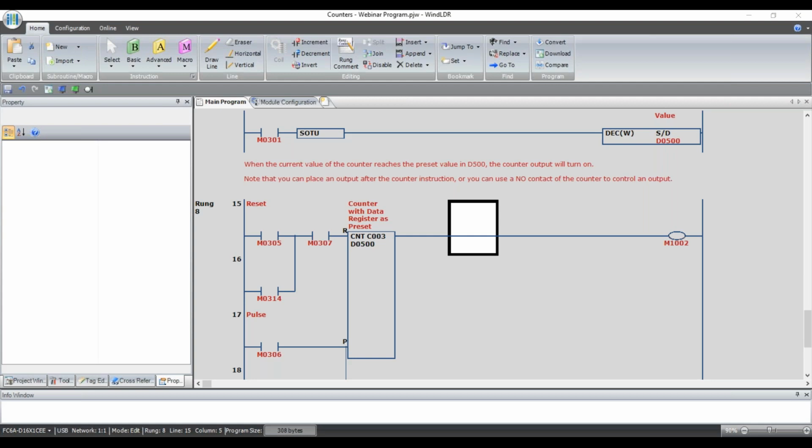They will work down to about, I think it's about 17, 18 volts. That's kind of the threshold of when they will turn on. So in other words, you don't have to give them exactly 24 volts. If it's 23, 22, 21 volts, it's going to turn on. As far as sending it a frequency, you know, we did high-speed inputs during one of the webinars, high-speed counters.